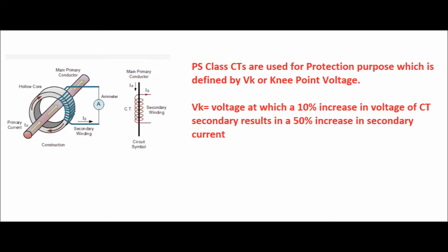So what is the definition of the knee point voltage? Knee point voltage is the voltage at which a 10% increase in the CT secondary voltage results in a 50% increase in the secondary current. This is the definition of the knee point voltage.